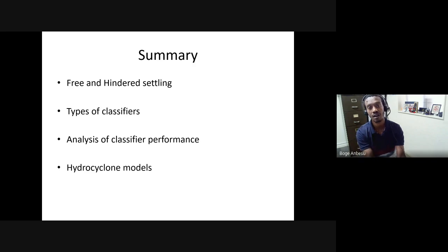Unless, as I said, you have a very impure water with very large suspended solids in it. Probably some other operations like flotation can be very sensitive to water quality, because some ions can interact with the particles, they can change surface chemistry, and we know flotation, for example, is surface chemistry dependent. Okay, so that can have significant impact.